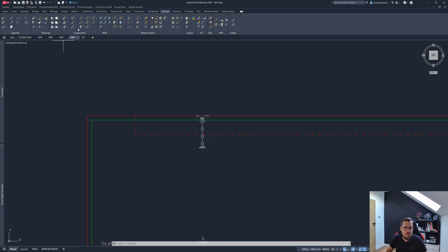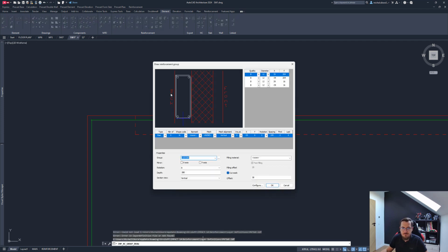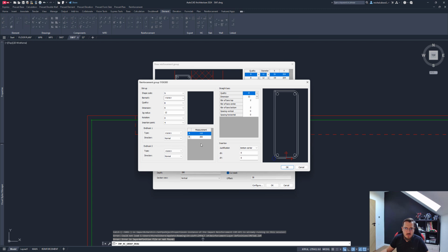So we can go ahead and actually do that reinforcement. Let's draw that group. I'm going to configure whatever I have here and change that slightly. So I want to change that shape. Since we have about 200 millimeters of a panel, I'm going to add here 170. Okay, that's that. And for height, since this is 100, 150 of height, let's make it 110 maybe. Yeah. And let's add more reinforcement here and here. Also, let's add hooks to that, so it functions more or less better.